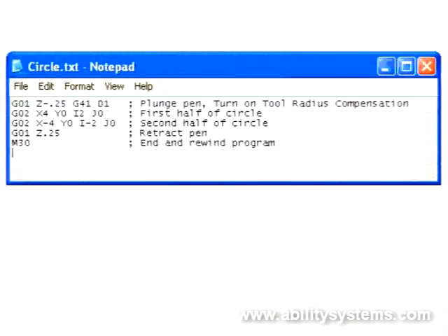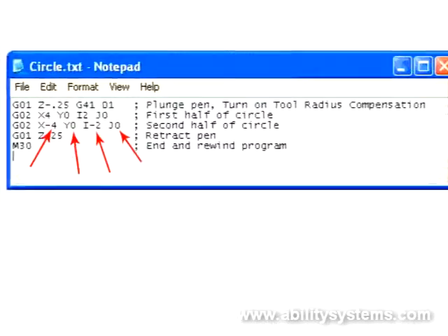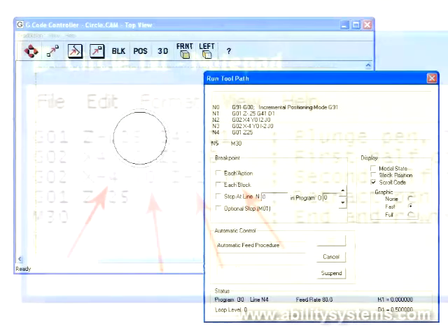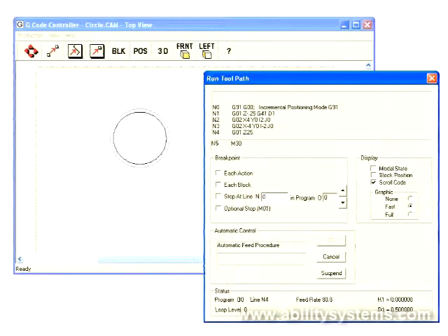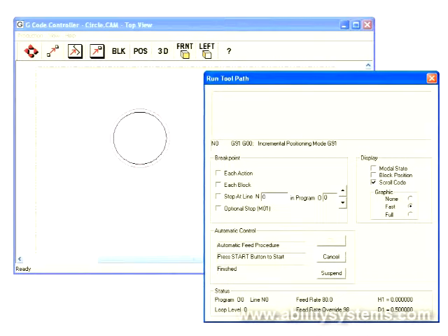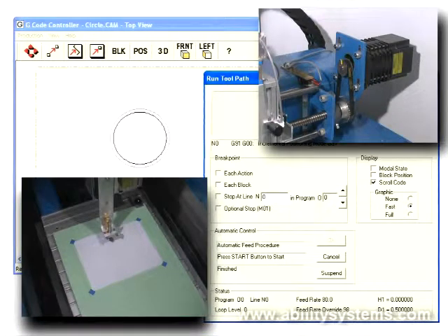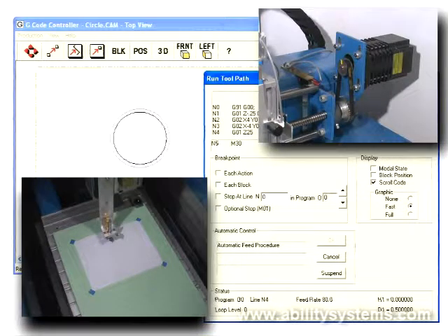This clip shows how a G-code script, with dimensions called out in inches, can generate a tool path that would cut a 4-inch diameter circle using a 1/2 inch diameter circular cutting tool. The application program calculates the straight line paths that are required, communicating these approximating line segments to the indexer. Indexer LPT assembles these paths end to end and smoothly generates the electronic pulses that move the machine over the desired path. Between the actions of dropping and retracting the stylus, you can hear the pitch of the control signals change as the motors accelerate over the circular path, traversing from one segment to the next, then decelerating to a stop.